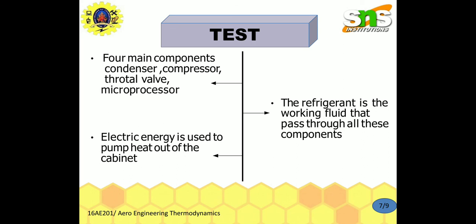For Carnot refrigerators and heat pumps, COP can be expressed in terms of temperature. For example, the COP of a Carnot refrigerator is the ratio of the lower temperature to the difference between the high temperature and the lower temperature, and the COP of a Carnot heat pump is the ratio of the highest temperature to the difference between the highest and lowest temperatures.